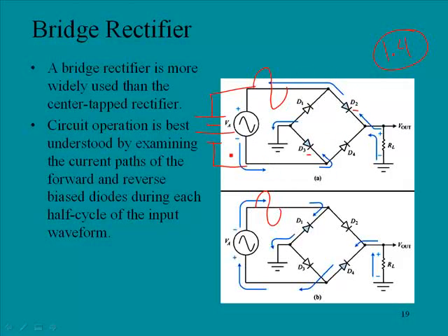Now, on the other hand, let's look at these 2 diodes. The positive is placed right here. Effectively the positive is only a 0.7 volt drop away, and the negative is right here. So these 2 diodes will be reverse biased, and these 2 will conduct. Now that's going to be on the positive part of the waveform, so we would have this resultant output across the load. Now on the negative side, again, if we draw the battery kind of like this, and we take a look at this.